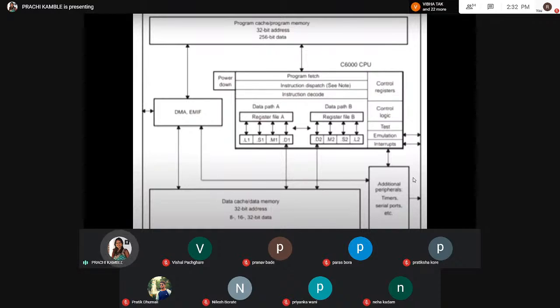And the second one is the extended DMA controller. The extended DMA controller works the same as your normal DMA controller. The difference between the DMA controller and the extended DMA controller is, in the previous case there are 4 channels plus one auxiliary channel, and in the case of extended, it has 16 channels, which perform the transferring of the memory and data. So this is the first unit of the peripherals.